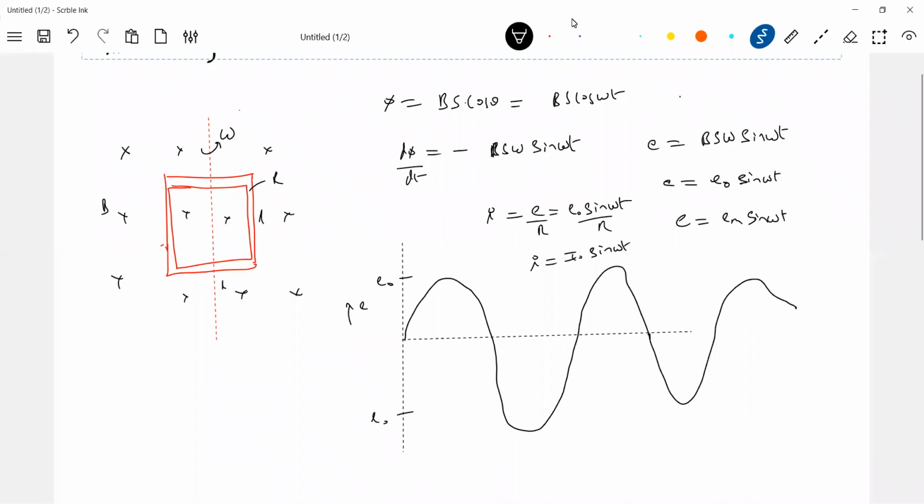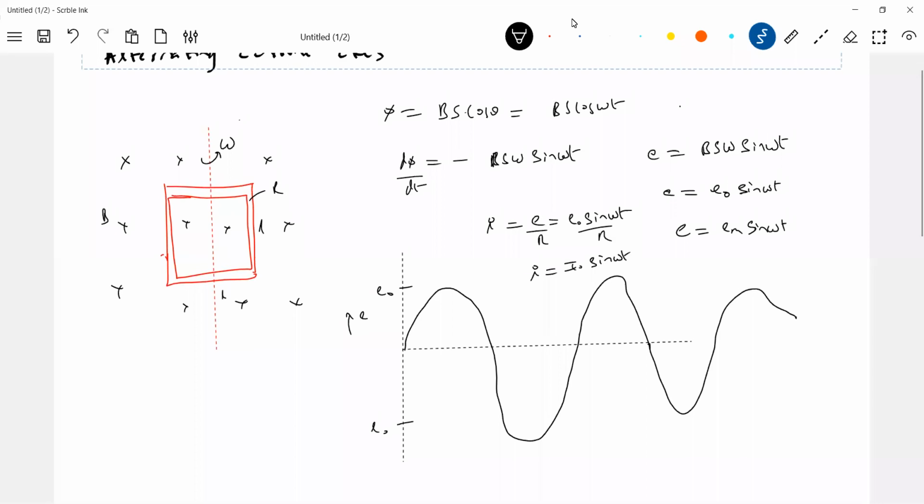So this particular rotating loop in a magnetic field will behave like a source of EMF. And look at this, it has a positive cycle. This will be the positive cycle, and the next one is the negative cycle. So like this, the current in the loop will alternate. That's why it is called an alternating signal. You see, positive, next you'll get the negative cycle, again positive. Again, look at this one. For every certain interval of time, the positive and negative cycles will alternate.